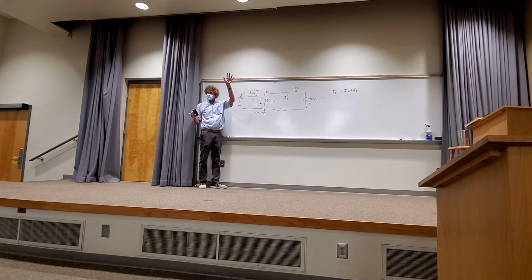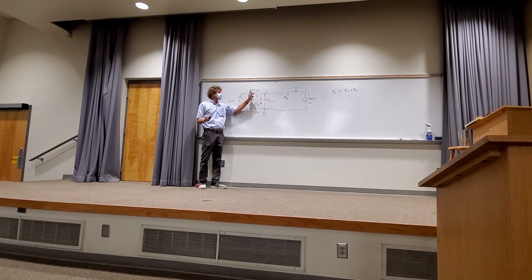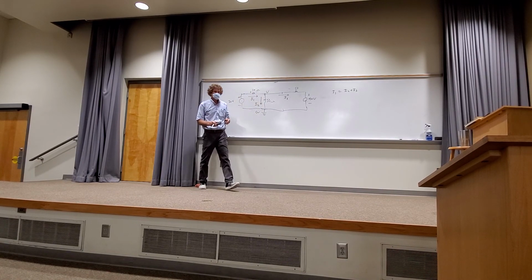How many see that? If you have a question, you can ask me if I'm not clear. The real thing is I'm saying we're using these voltages for one reason, to get the currents, aren't we? So the voltage difference across that resistor driving the current would be the voltage on this side minus that side, divided by the resistance.